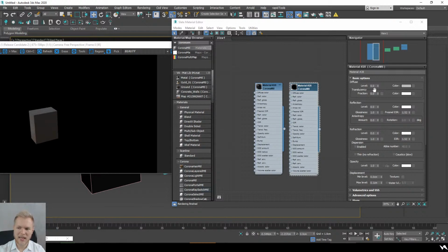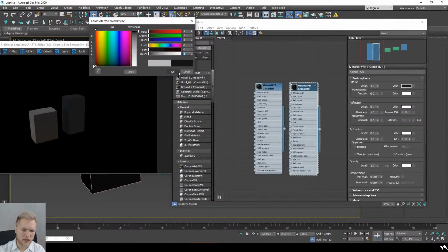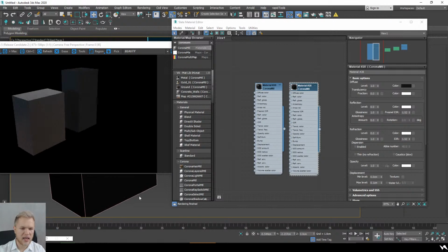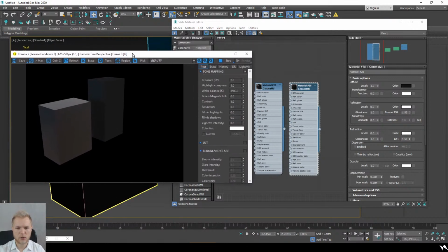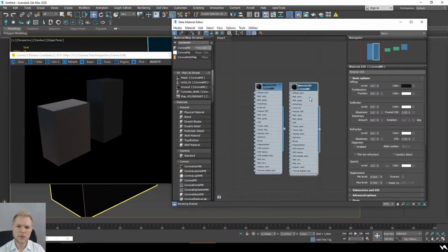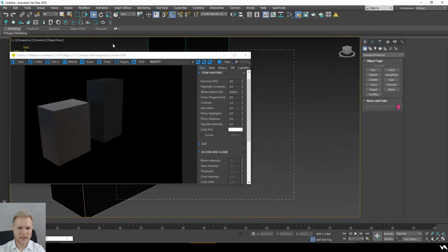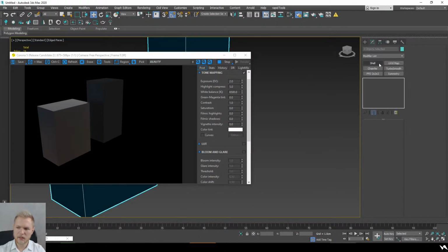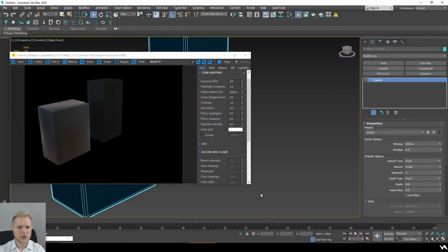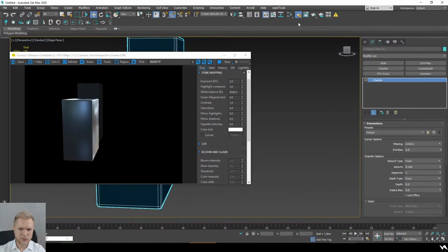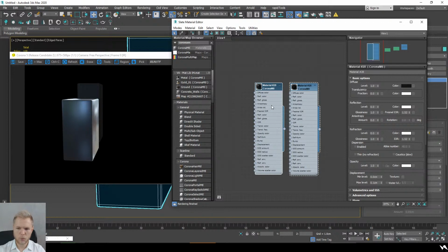Because it doesn't bounce any light back. But once we add just a hint of black color, so it's just 1, you can see it again, because now it's taking part in our calculations. So this is very important for us, because we need at least a little bit of diffuse color in there, so it's going to look better. So this is what you are aiming at when doing materials like that.